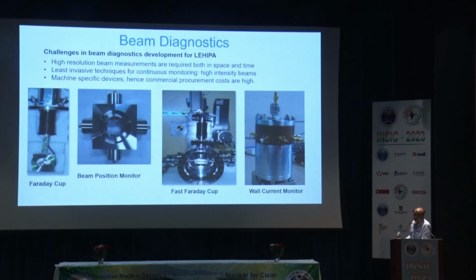Well, on the front of beam diagnostics, we have developed almost all type of systems here with the local industry, designed in BARC. For example, this Faraday cup, this is an interceptive device, this cup goes into the beam line and intercepts the protons, and that current is measured. But all other devices, they are non-interceptive. Beam position monitor, fast Faraday cup, wall current monitor. They can capture the bunches up to even 500 picosecond or less.